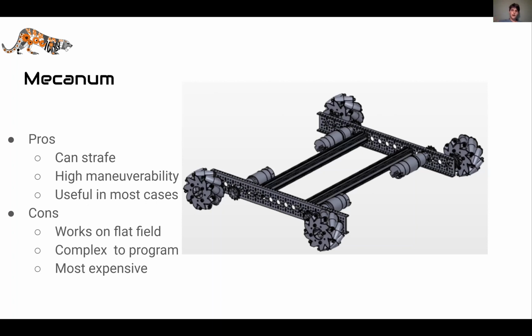And that can be used if you drive those wheels against each other. Those rollers will actually slide the robot along the direction that those rollers are facing. And you can get strafing or side-to-side movement, but you still retain a decent amount of traction. So good things about these, it's only 4 wheels, 4 motors, high maneuverability, pretty decent traction.